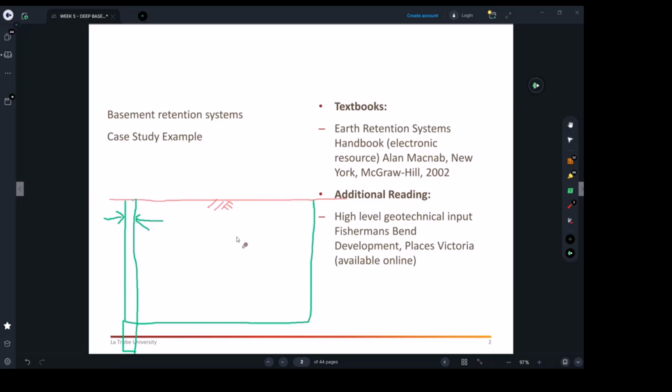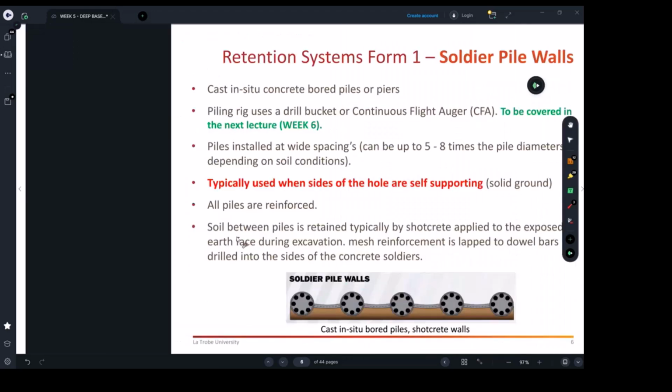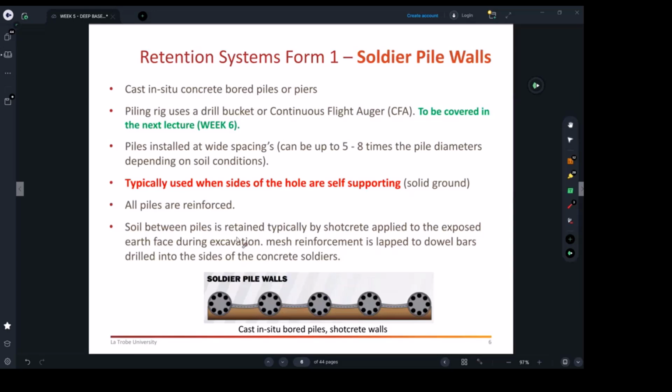Now, when they build, sometimes we've got a fill and we have to build a house on top of that fill. We use bored piers where we don't need to reinforce them because we just want them to take compression load. We don't want them to take flexure. That's different. We're not studying this in this subject. We're studying the members which are under flexure.